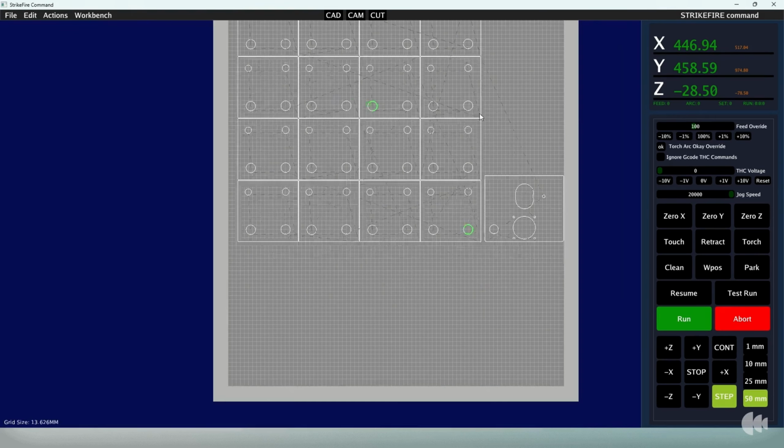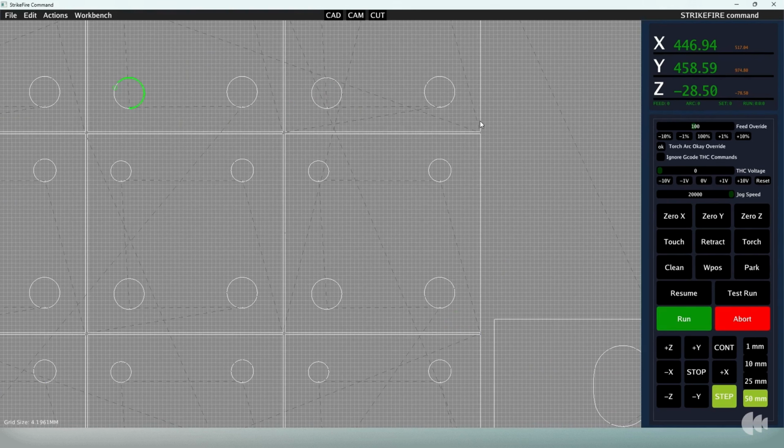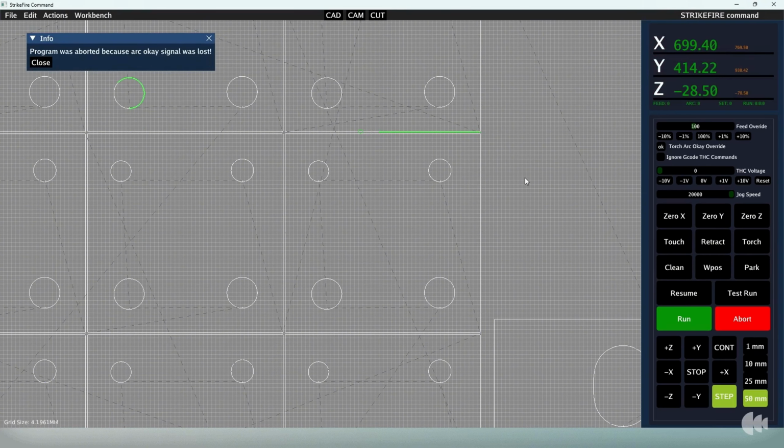It also has the ability to change the direction. So if we just started on here, move there, let's say it starts cutting, it'll normally cut in its normal direction. Let's say that for some reason it stopped on a big part. This is a big issue on a lot of other CNCs. If you're halfway through a cut and it's like a meter long cut, and for some reason it ran out of air, or the compressor had an issue, or the plasma stopped for some reason, it's very hard to restart. On ours, it's very easy.